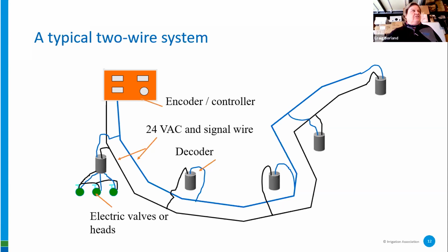That 2-wire path has that voltage flowing on the entire path while zone 14 is running, which means that 2-wire path is live. In many cases, that 2-wire path is live 24/7, 365 days a year, including holidays. It's running all the time. For in effect, if you had a moisture sensor, a flow sensor out in the field, and the flow sensor detects unexpected flow, hey, that valve all of a sudden decided to turn on accidentally. The flow sensor would tell the clock and the system would shut down.